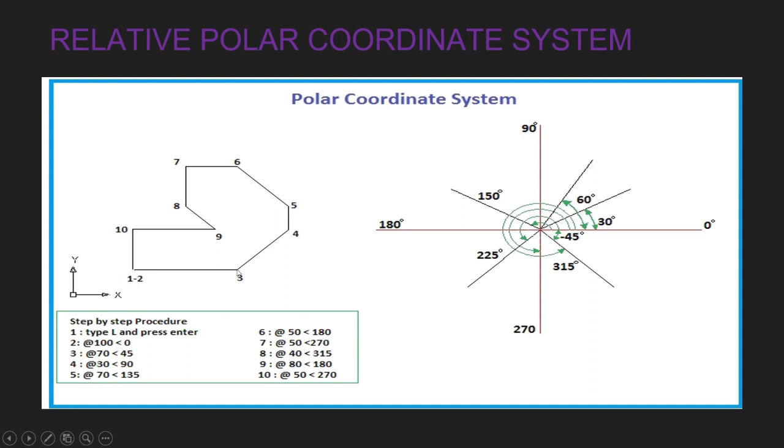Again I'm going to draw 70. So the length of the line is 70 and the angle is 40, so it will lie like this. Likewise I will draw the steps to draw these lines. This is how we draw using relative polar coordinates. We can use all three of them in current AutoCAD, but mostly we use relative rectangular because we use the mouse nowadays. Before the mouse, we used the keyboard alone. Using commands only, we could draw. So this is the way we draw AutoCAD lines.